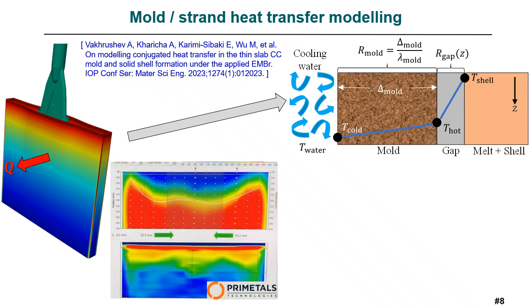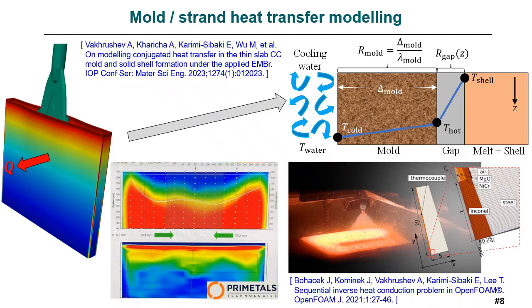To account for such phenomena in the numerical simulation, we need extensive industrial data, such as temperature measurements at the real casting line, or experimental data, for example, for secondary cooling zones, where the performance of the water nozzles is estimated based on the inverse heat conduction problem.